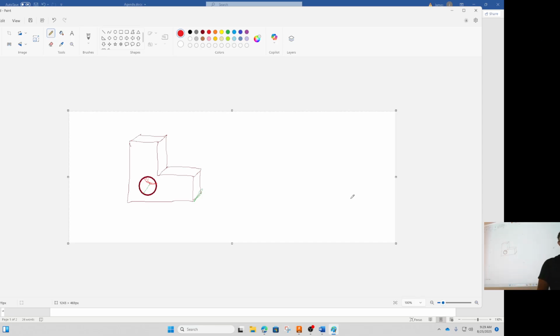So in oblique, is there always a front face? In oblique, there's always something you're looking at straight. Okay. And remember, this face doesn't have to be the front of the part, but usually it's the one that's most descriptive. There should be a flat face, something flat.